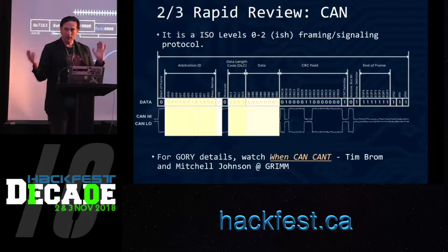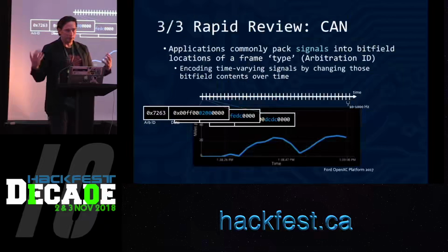So these CAN frames are flying around your vehicle. You have a whole bunch of ECUs all connected together. And it's important to remember, why did they even bother putting a CAN bus in a vehicle? Before CAN buses and ECUs, you would have multiple sets of analog signals going back and forth in the vehicle, okay? And these analog wires would carry individual signals, like whether your windows are up or whether your door is closed, or where you had your foot on the accelerator pedal? In some cases, otherwise it's vacuum pressure, but in some cases it's measuring a particular signal, okay?